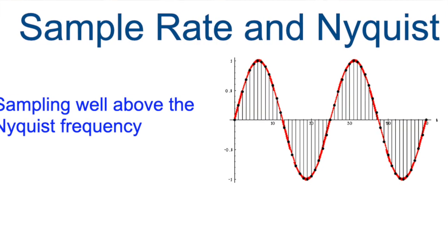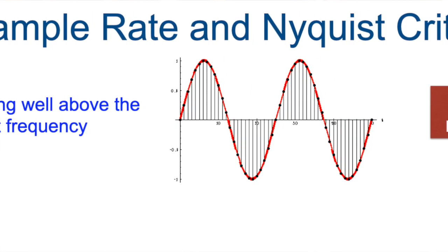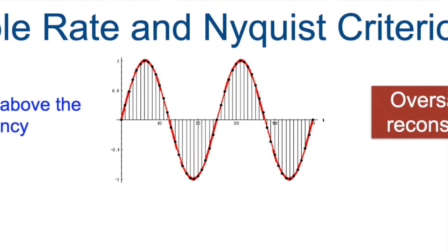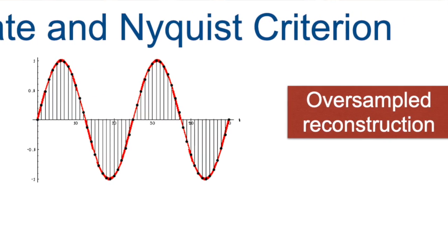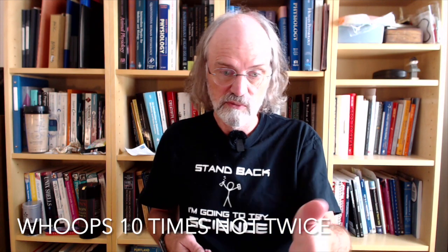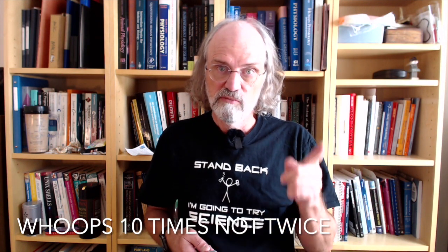So if we look at this example here, this is a situation where we have two full cycles and something like 20 maybe samples for each one of the cycles. There's probably 10 samples in each one of those positive and negative halves. So we have a sampling rate that's much more frequent than we need, because we know we only need 2 samples per original highest frequency component that we have in our signal. That's what the Nyquist criterion actually says. And again, read about that in the textbook. It's important that you at least understand what it says.